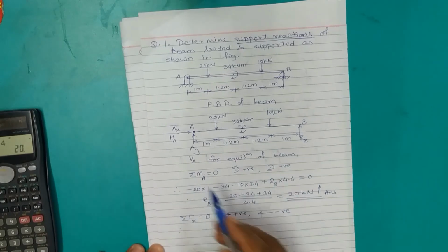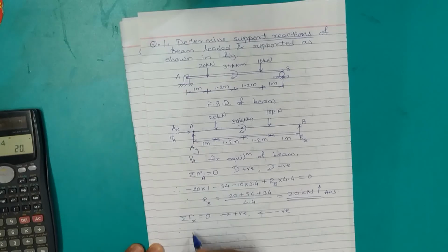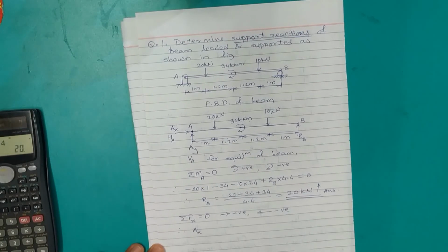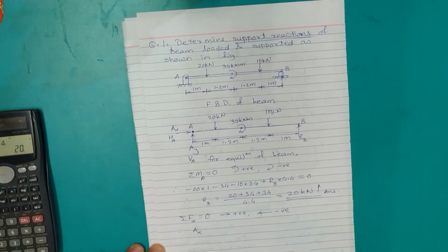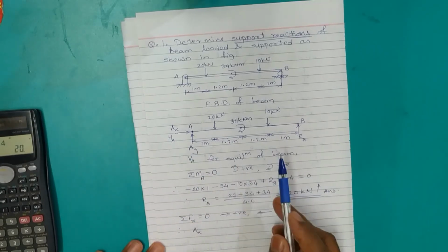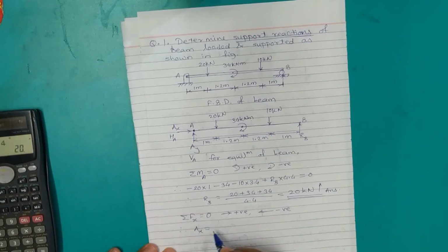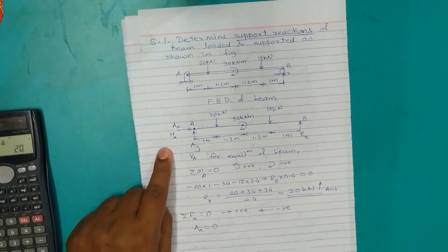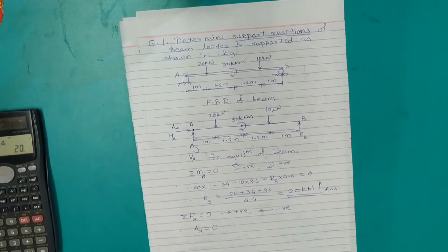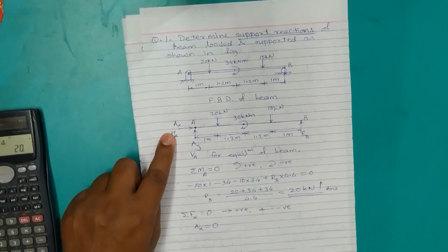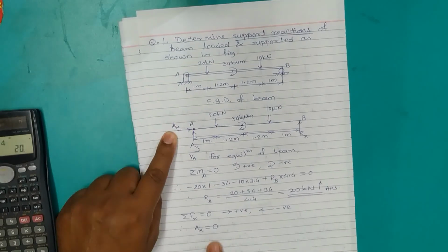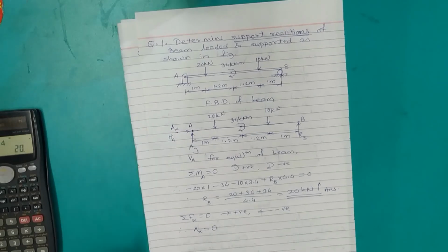So then we have AX assumed going in the right direction, and that is the only horizontal component existing in the system. There is no other horizontal force to balance it, to nullify it. So on its own AX has to be 0. If there is equilibrium, the only horizontal force existing in the system has to be 0. Here you have applied the single force principle, where for equilibrium, if there is a single force existing in the system, it has to be 0. That is the single force principle. So AX is 0.